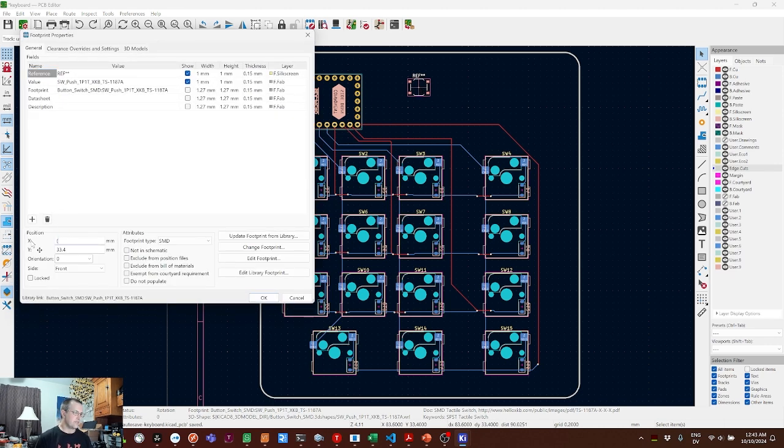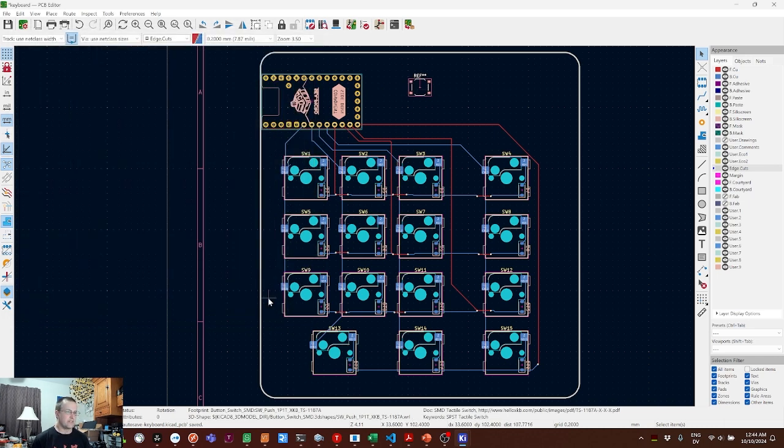So I'm going to double click on the component to set its position numerically, and I could do the math here, or I could have KiCad do it for me. Average 137 plus 31 divided by 2 should give us the point between those two numbers. And we're setting the center of the component, so it should be nicely centered right there. Beautiful.